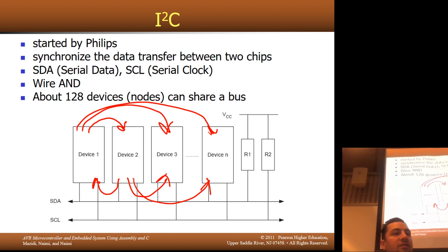So you need to have this ability to understand when the bus is free, okay? Because if you're talking, device 1, say, is talking to device 2, and device 3 decides it wants to talk to device N, that's not allowed at the same time because it's a shared resource. This is shared across all of them. So device 3 has to wait until device 1 and device 2 are done talking. How does it know when it's done talking? It sees a stop condition. That's it. So that's why we have start and stop conditions.